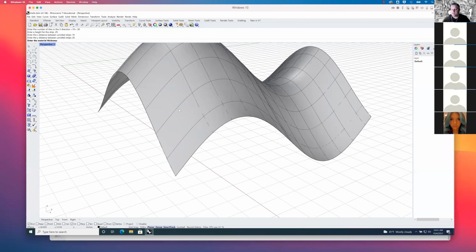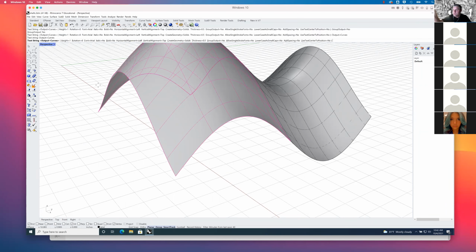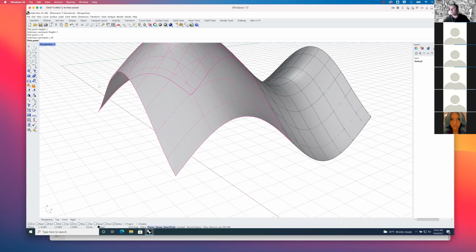And then the material thickness. We'll talk about this in a bit when I measure some 1-ply chipboard, but I'm just going to say 0.03. Let's just say it's a 32nd of an inch, so that would be 0.03125 or something like that. I can't remember offhand, but I'm just going to say 0.030, and let's see what it does. Now you're going to watch, it's going to go through here, and you can see the command line is scrolling through. I've turned the redraw off because it goes quicker if it doesn't have to redraw things in real time.